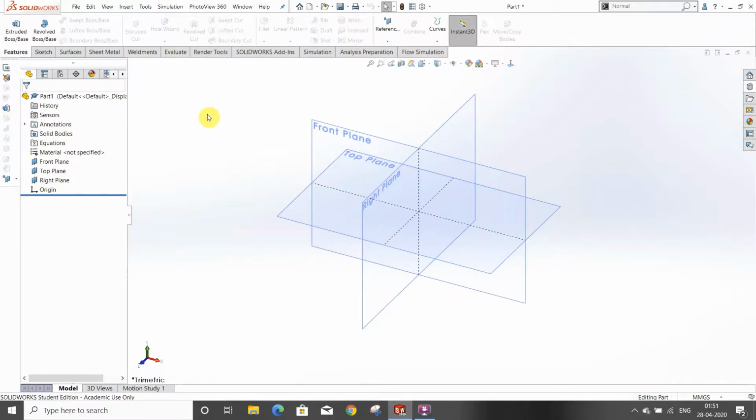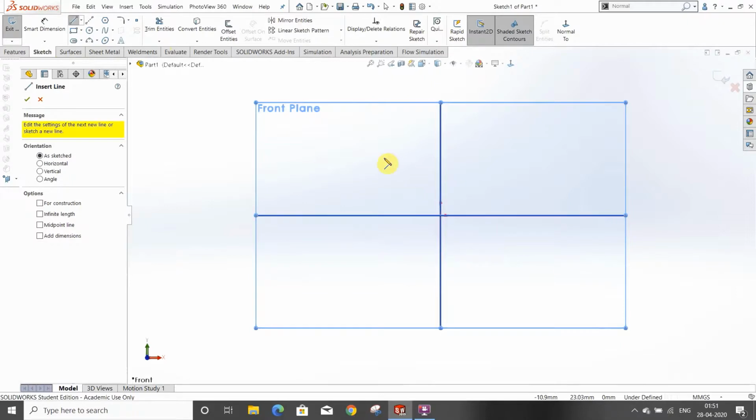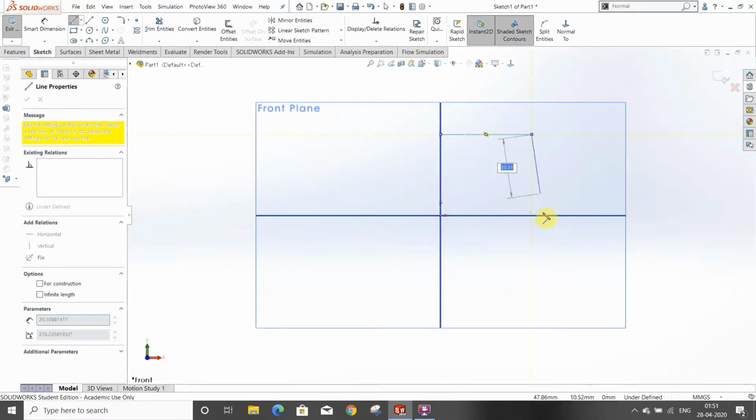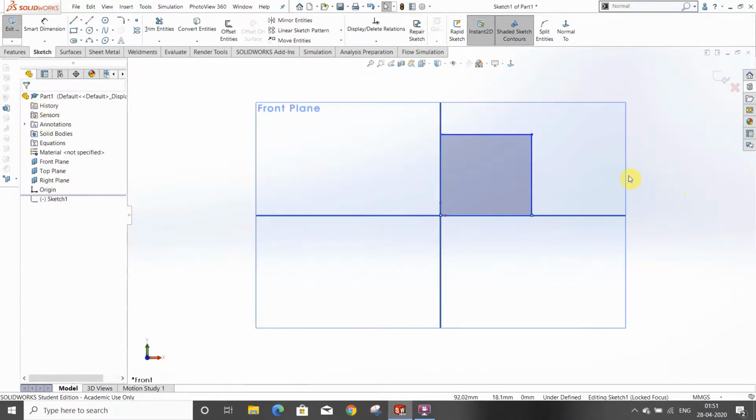That's fine for this video. I will show you how to sketch. To start sketching, you need to select the plane and click on sketch, or you can click here and select the line option, and it will align the plane to normal view. Then you can sketch a line. To cancel the command, you need to double click on the white area, or you can just click here.